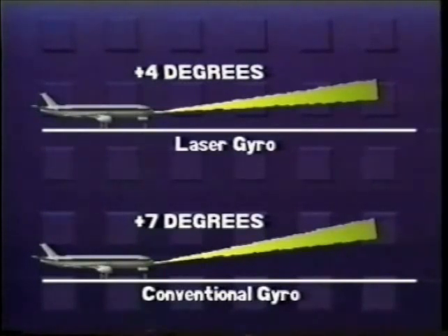For aircraft with conventional gyros, the acceleration error will continue until the aircraft reaches a steady-state airspeed. Once the aircraft is in a steady climb, it will take approximately 3 minutes for the vertical gyro to stabilize and provide the radar with a correct attitude reference. As a rule of thumb, on climb-out, pilots should reduce the initial tilt setting by approximately 1 degree for each 10,000 feet of climb, or until ground returns appear on the outer edges of the scope. Once the ground returns are presented on the outer edge, small adjustments to the tilt can be made to maintain that presentation.